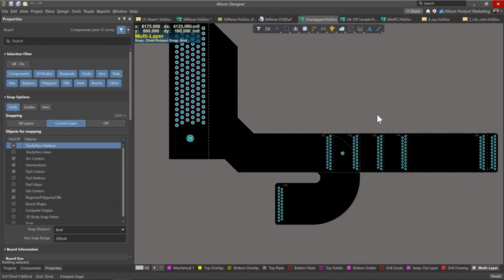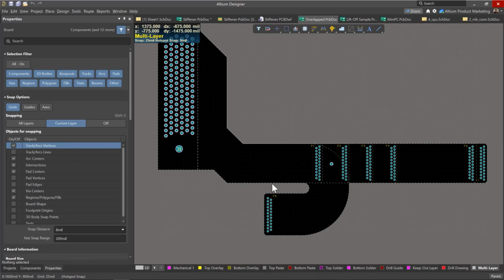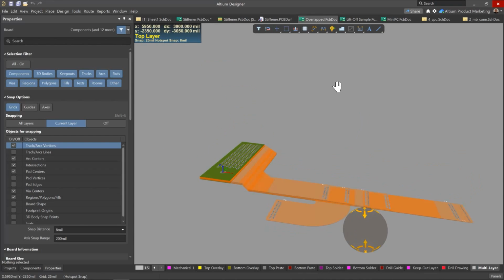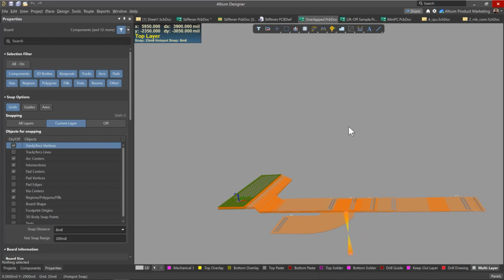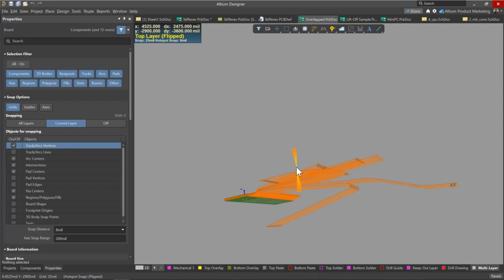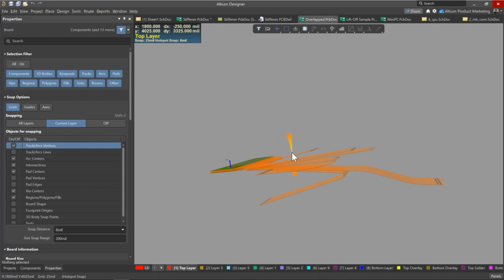If we switch over to 2D, we see the whole design with these connectors. We come over to 3D, and as I move this over here, I can hit 5, and it will show us the fully flexed board. We see here there are the overlapping regions, and the bend lines, as they are defined by region type. Even though these are overlapping, we were very easily able to associate the bend line to the different layers and have this split.